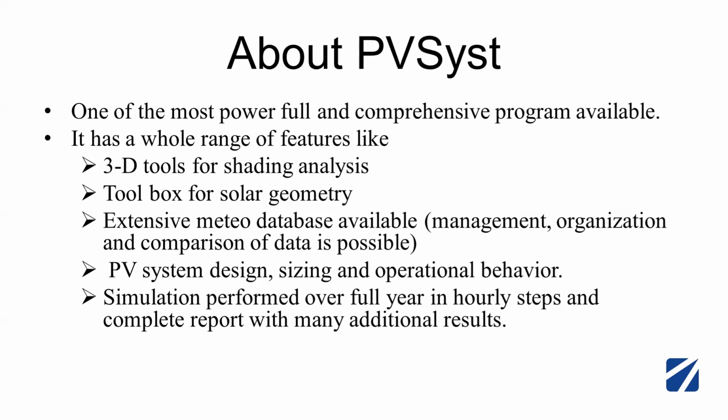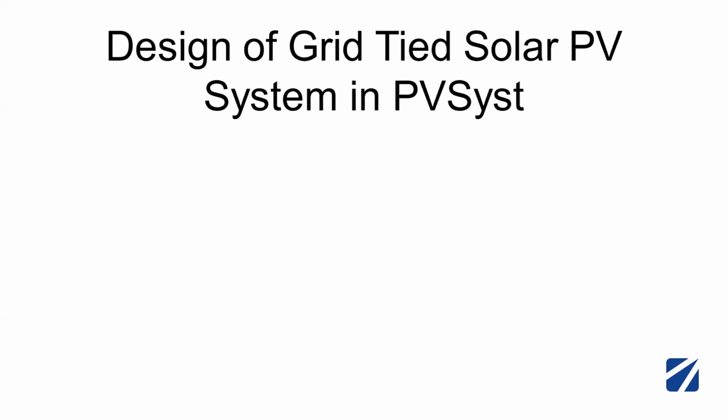And PV system design, sizing, and operational behavior. Also simulation is performed throughout the year in hourly steps, and it completes the report with many additional results. So many, like what is the performance ratio, what will be the capacity utilization factor, these things we can also get. And then let us start with designing a grid-tied PV system in PVSyst.